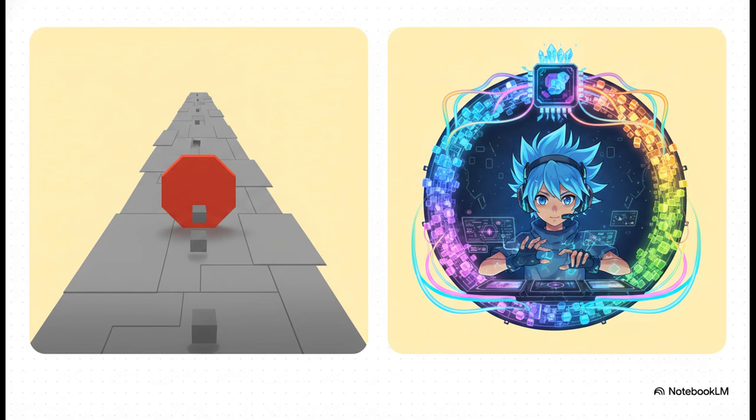Now, when you're actually configuring DMA, you have a pretty important choice to make. Normal mode is basically a one-and-done operation. But circular mode, that brilliantly loops your buffers. Once the DMA hits the very end of the buffer, it just automatically reloads the addresses and starts right back at the top.